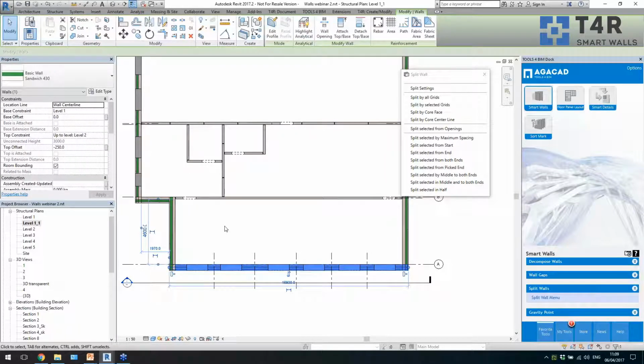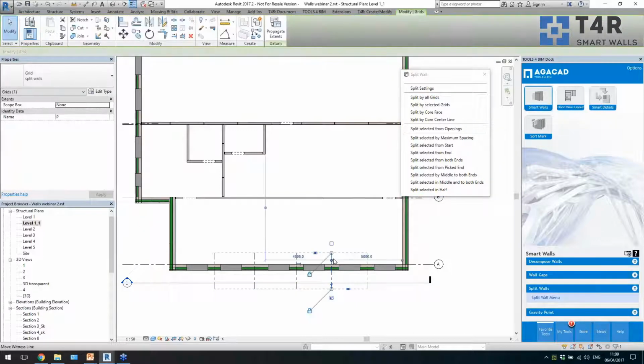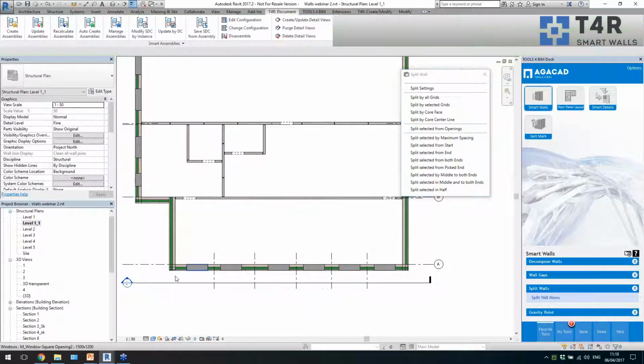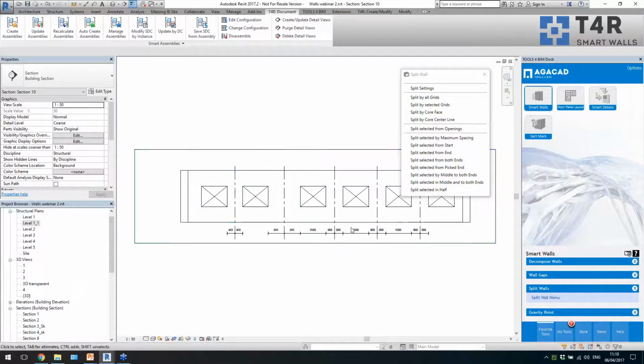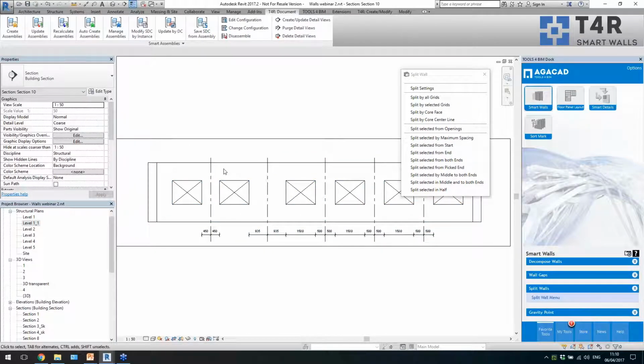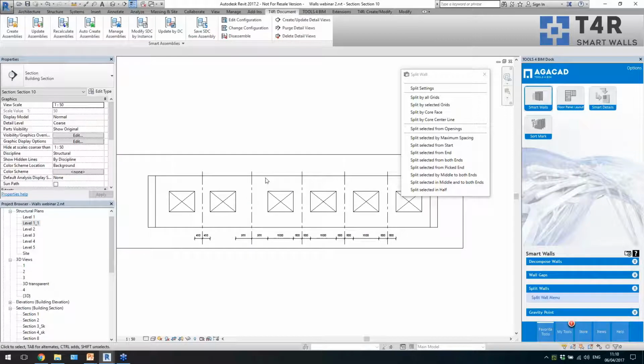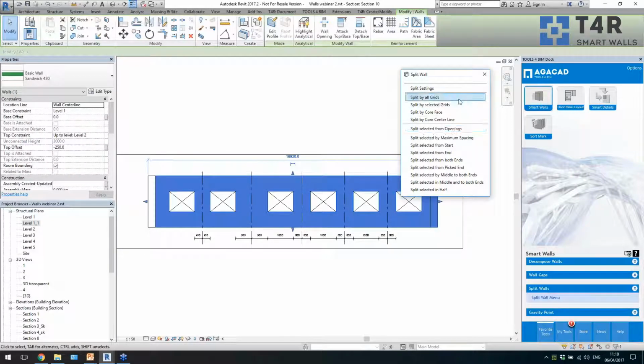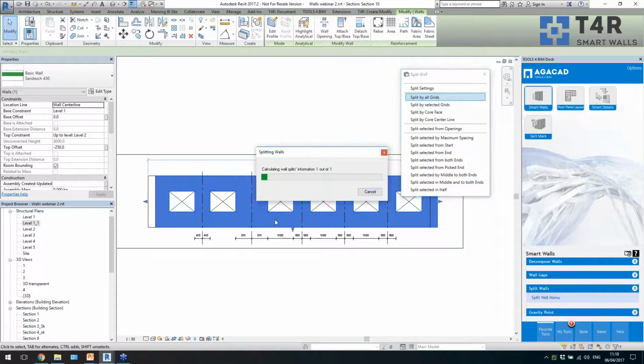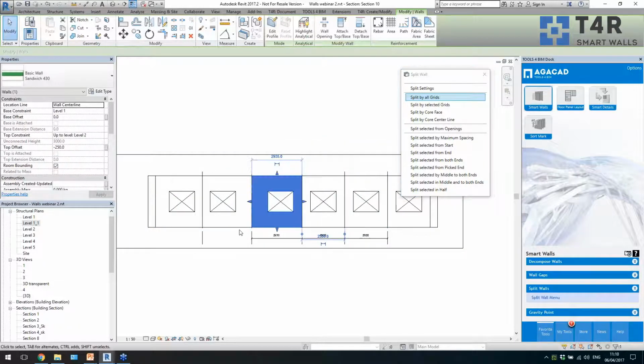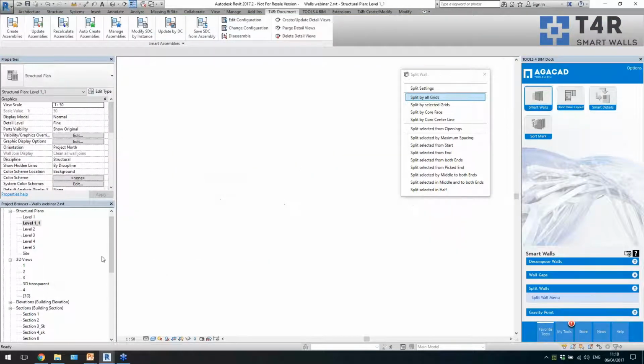Let's say I have this wall, right? So I can split it by all grid lines. I just used a different type of grids, not the building grids, but an additional type of grids. I will use them temporarily just to split my wall. So I can plan it, add dimensions, send it to someone else who needs to confirm it, and then split walls by all grid lines. And now you see I have these separate panels divided in the grid locations.